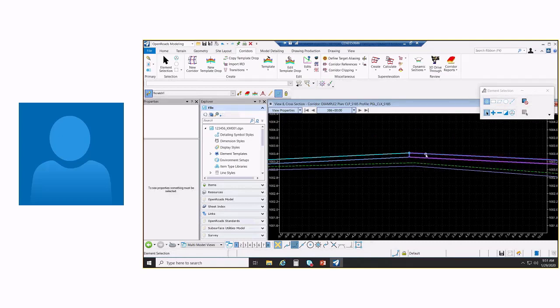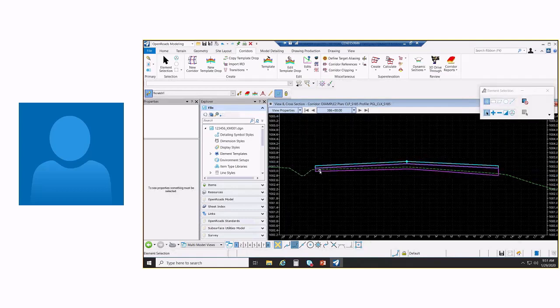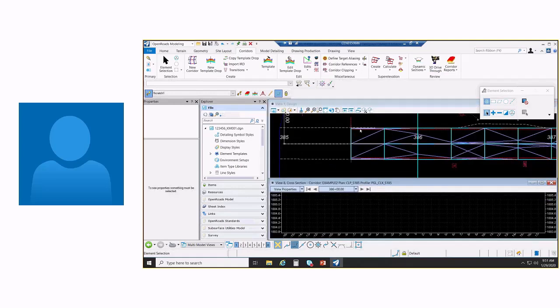So I've got those 2 components, and then here's that wedge course component that's going to just trace the component itself that I drew as the top, and then going down 1 inch off the bottom. So that's the other type of component that you can use in widening and resurfacing. You've got the stripping component, and depending on how you define its top and bottom, you can define it as filling in between what's stripped out and the bottom of your pavement itself. Okay. Any questions on that one at all?